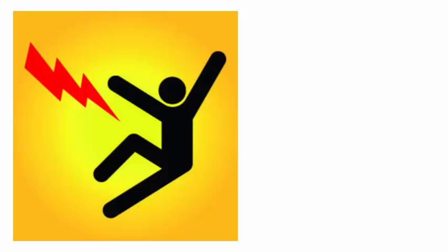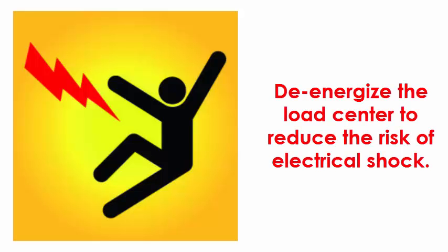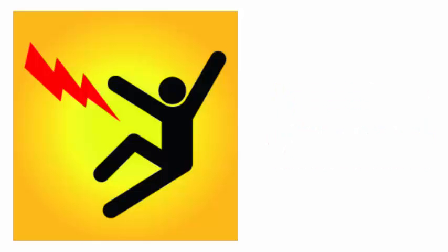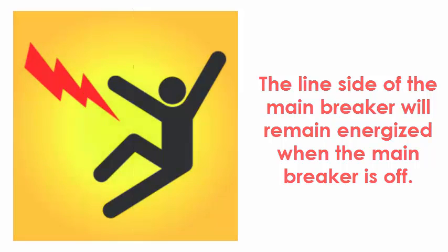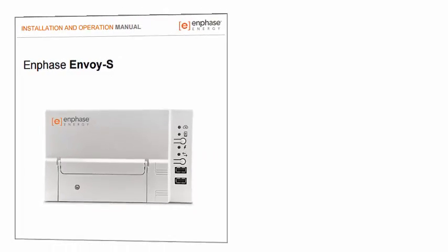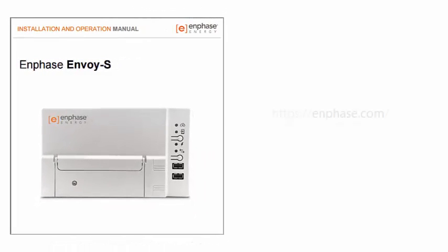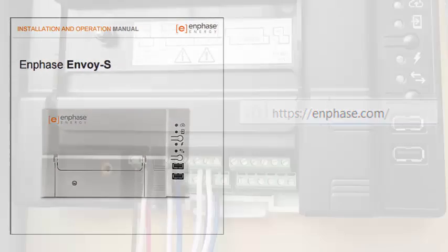Before installing CTs, always de-energize the load center to reduce the risk of electrical shock. Be cautious. The line side of the main breaker will remain energized when the main breaker is off. For additional safety information, please reference the Envoy S Installation and Operation Manual on Enphase.com.